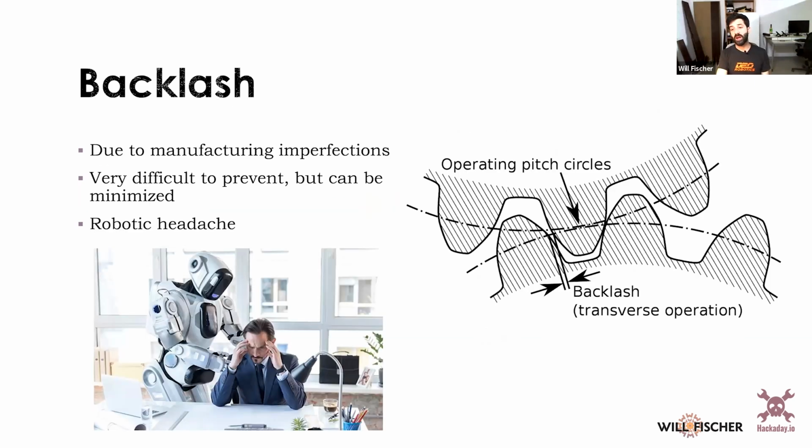When you have gears operating together, you end up with backlash. If you're rotating in one direction, you get this perfect synchronous motion. As you rotate back the other direction, it takes a fraction to move. That's something to pay attention to as you get more and more gears together, because the backlash adds up between them. If you have only 2 gears operating, you have some backlash, but if you run that same gear system back to back to back to back to back, you now have 5 times that much backlash. You're going to start spinning in one direction, and when you reverse it, you're going to spin maybe a quarter of a rotation before you actually start moving the other direction.